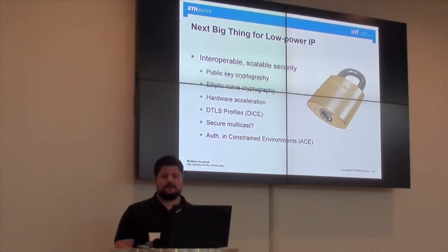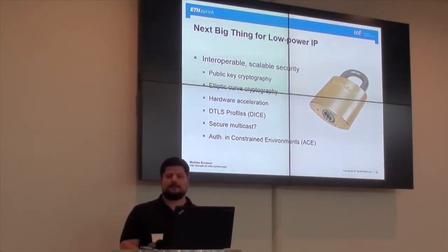You basically have to look around, because the motes, this T-Mote Sky, are incredibly expensive. One thing is there's a combined humidity and temperature sensor, which alone costs $20 or $30, and the whole thing is $150. Still, you have to invest like $50. The cheapest I found were some AVR modules for around 10 euros from Dresden Elektronik. The nice thing was that they have a nice footprint. They are about this size, and they have small pin headers, so it's easy to just connect different sensors. They are small enough that you can build real prototypes, so much better than the rather big T-Mote Sky.